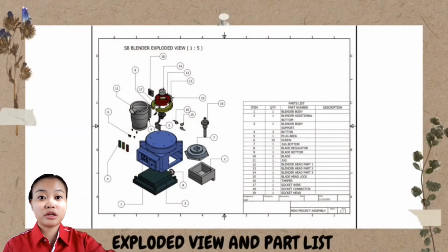A little explanation for exploded view: it describes assemblies by moving components out from their assembled position. We can use exploded view to balloon an assembly using item numbers found in parts. We can create exploded view by using a combination of assembly, which is IAM, presentation, which is IPN, and drawing, which is IDW or DWG files. View assembly is created in the presentation view and the components are repositioned in the view. As you can see on the exploded view, there are balloons that indicate which part has that number, like on the part list.